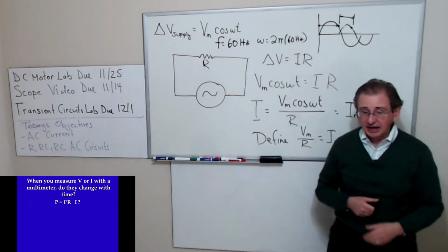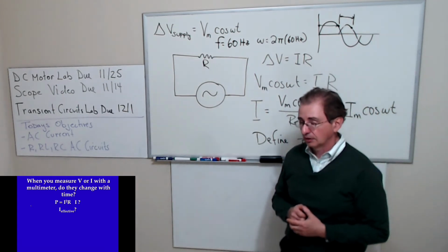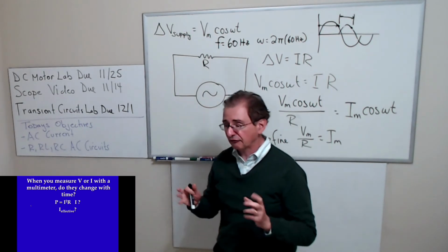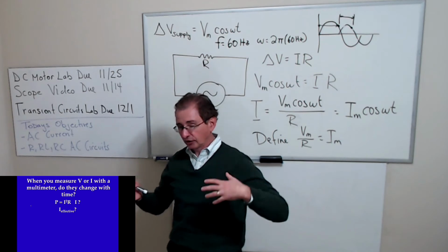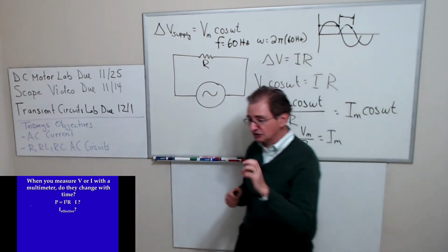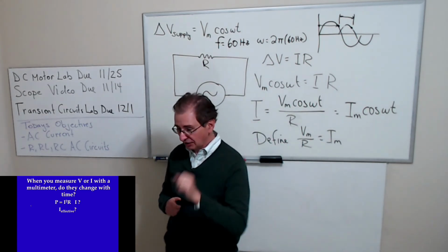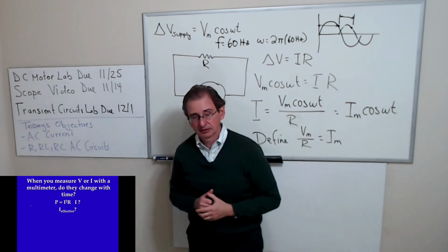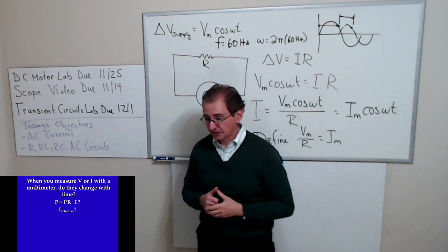Now the power is I squared R. So what would be I effective over a cycle? What would be the effective current over a cycle? Well, you'd have to figure out the average of the power, which means you have to figure out what the average of I squared is. And that's not 0, because I squared is always positive.